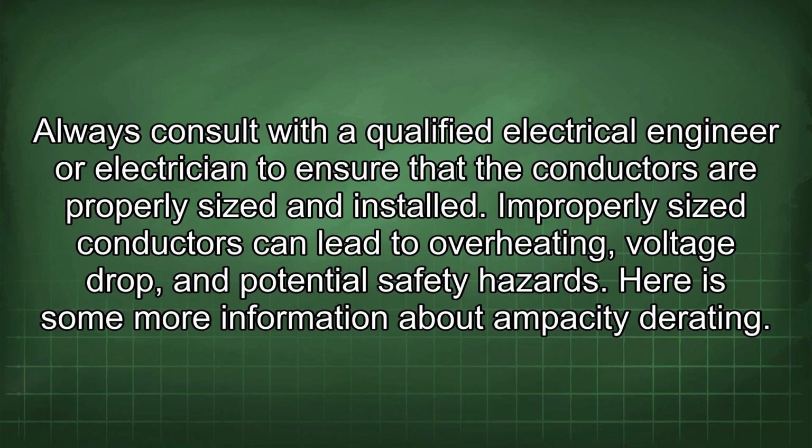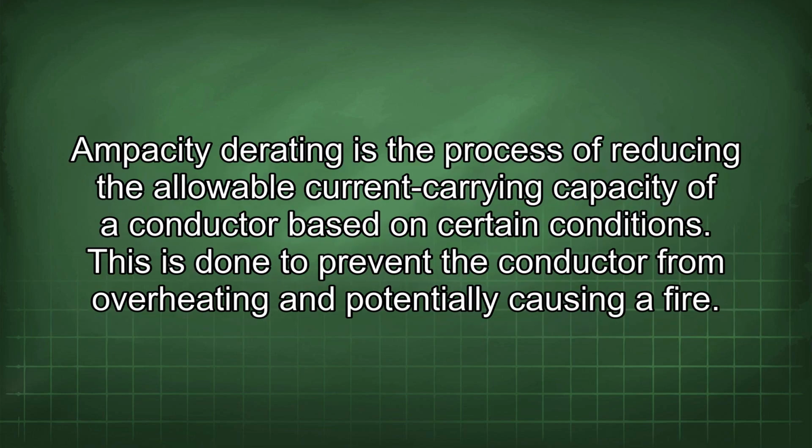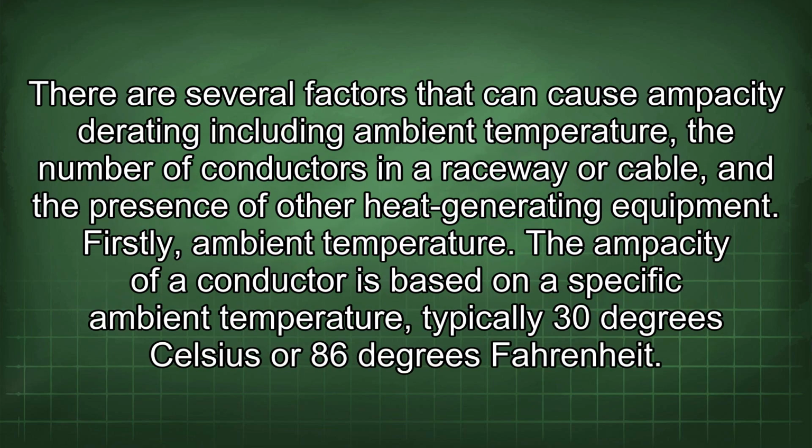Here is some more information about ampacity derating. Ampacity derating is the process of reducing the allowable current carrying capacity of a conductor based on certain conditions. This is done to prevent the conductor from overheating and potentially causing a fire. There are several factors that can cause ampacity derating, including ambient temperature, the number of conductors in a raceway or cable, and the presence of other heat-generating equipment.